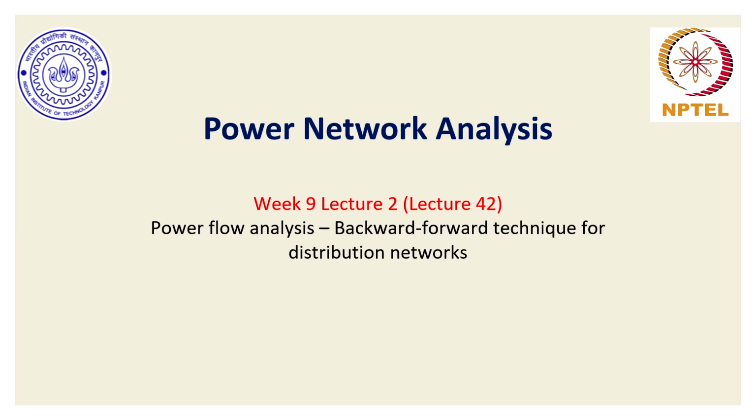And we have extensively talked about solving these equations for steady state analysis of the typical transmission network, which is meshed, has low R by X ratio, and the assumptions behind power flow analysis about the network: that the network is balanced and can be represented in a single line diagram on a per unit basis. With those assumptions, we have discussed the techniques involved in solving power flow equations for transmission networks.